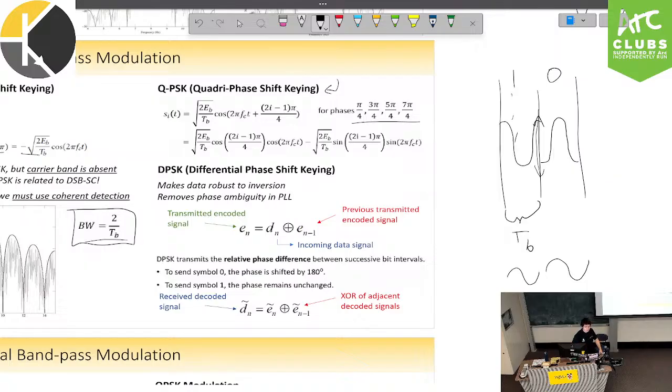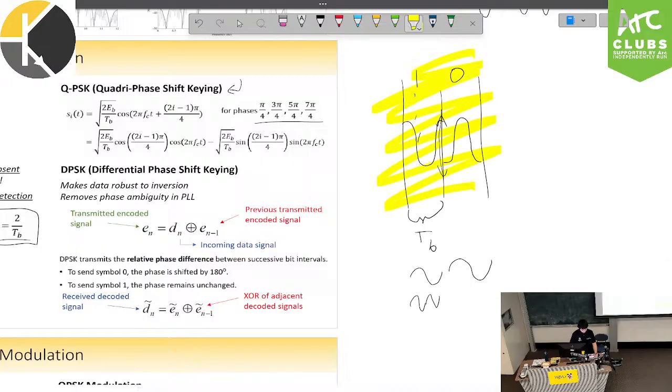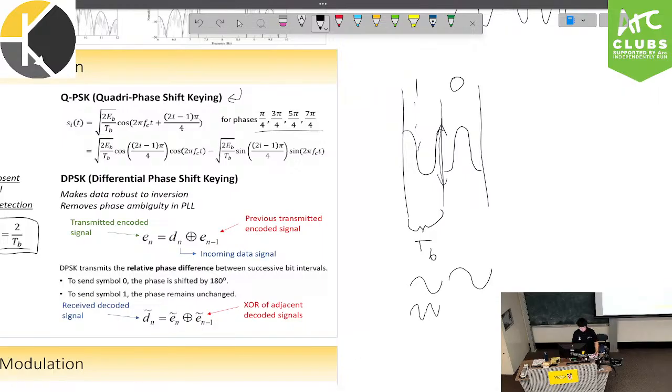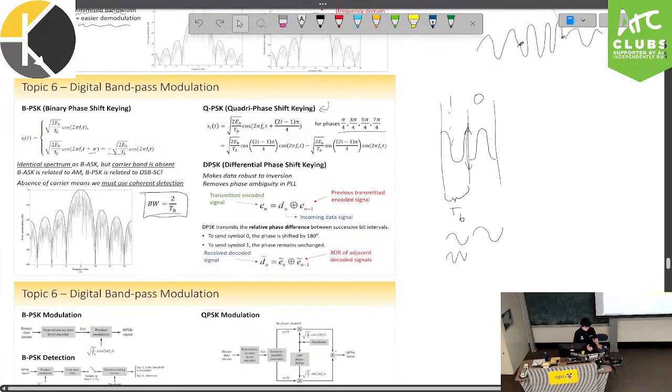So for the bandwidth, are you just like have the frequency for the 1, frequency for the 0, which are both 1 over TB, and you're just adding the 2 together to get 2 over TB? Kind of, yeah. So you're pretty much identifying that. The idea is, to my understanding, that you need a higher bandwidth in order to properly identify the modulated signal.